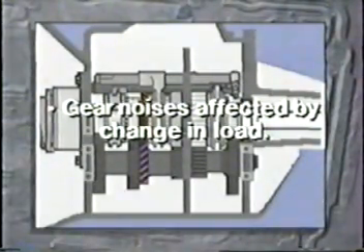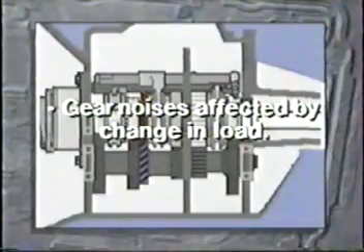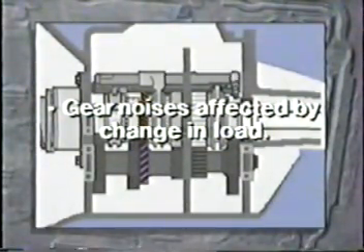Gear noises usually change and may disappear entirely when the vehicle is coasting or decelerating. In most instances, the gear noise will have a definite quality of sound difference between acceleration and deceleration.